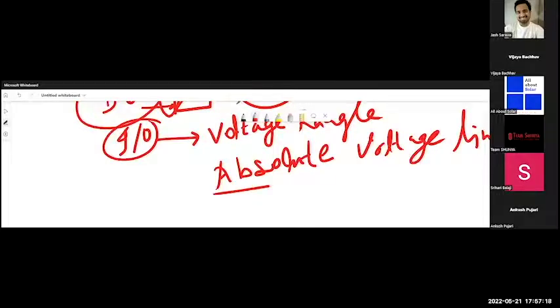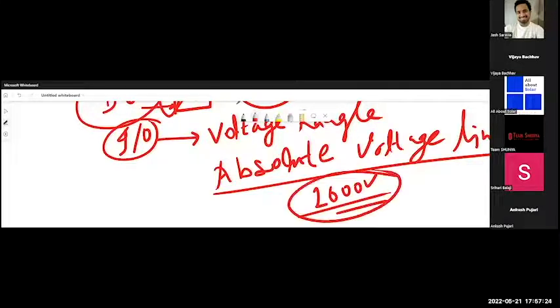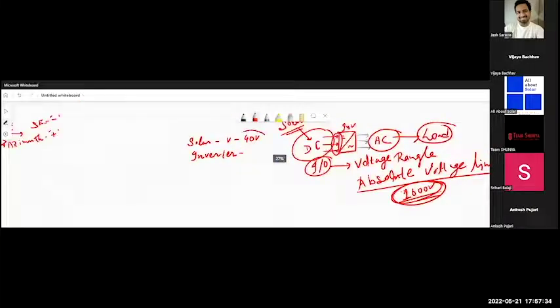In solar plant designing, this generally comes up as 1000 volt for a normal string inverter. So you have 1000 volt, right? And each module has 40 volt. So how many modules can you connect to a single string?